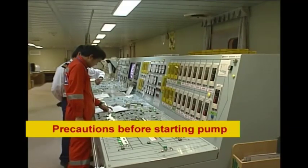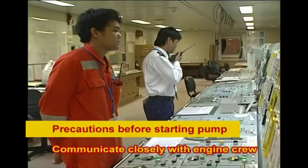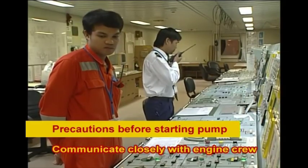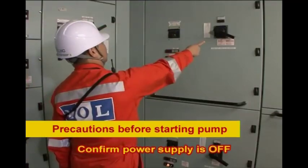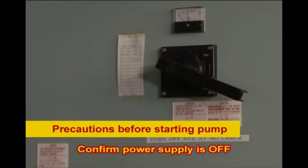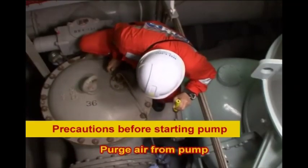Before starting the ballast pump, attend to the following. Communicate closely with the engine crew to avoid any accident due to lack of communication. Confirm that the power supply is switched off. Purge air.